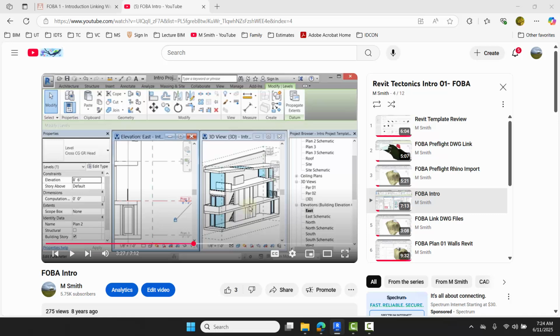So basically what's happening is the model elements are hosted on these levels, and these levels control where they are. It would make it very easy to change the plate height of your building, right, on the fly. Instead of having to go in and shorten everything, you can come in and actually move the level and everything on the level moves.